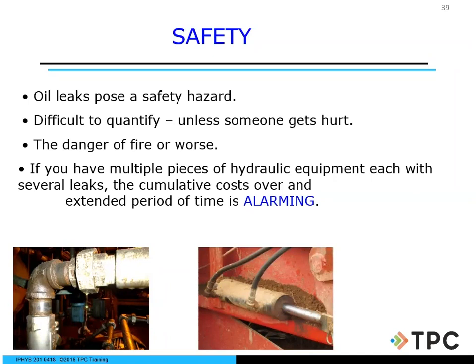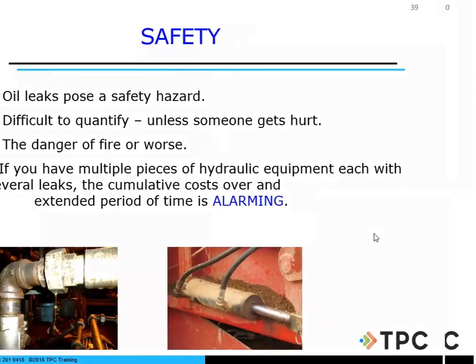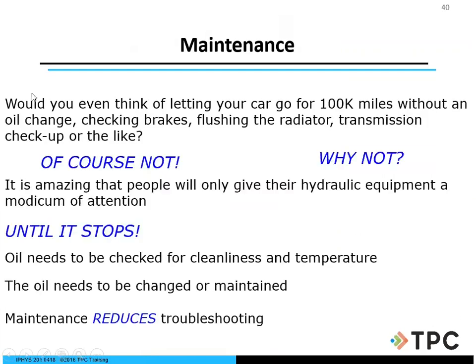So look at your entire system. Some people think that, well, it's hydraulic, it's supposed to leak. No. With the current fittings, the technology that's behind the fittings that we have in the 21st century, there shouldn't be any hydraulic leaks out there. So we need to put more effort toward that and take a second look at the hydraulic leaks that we have in our system. Would you think of letting your car go for 100,000 miles? No. So we're going to be changing and looking at our fluid.